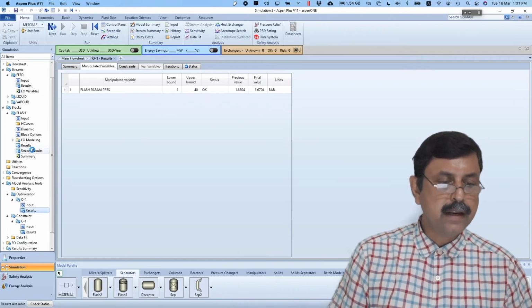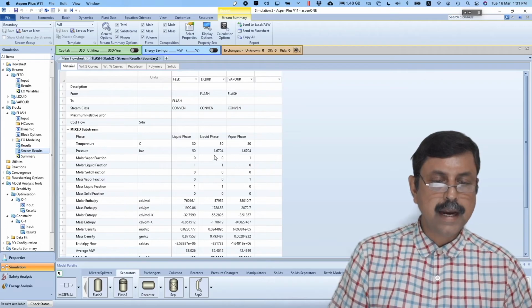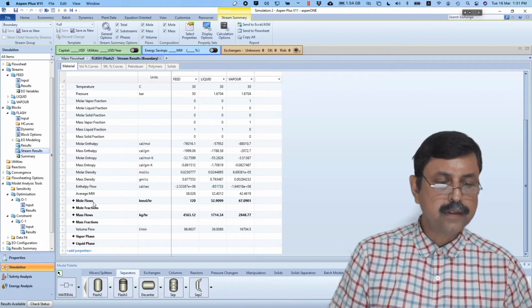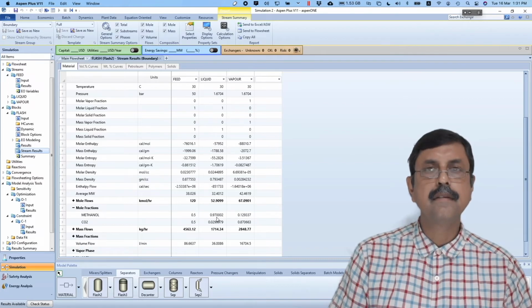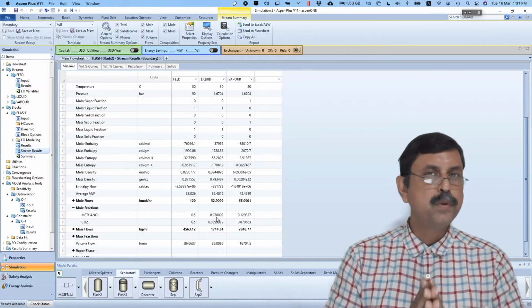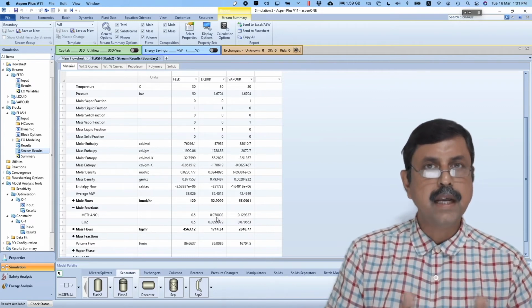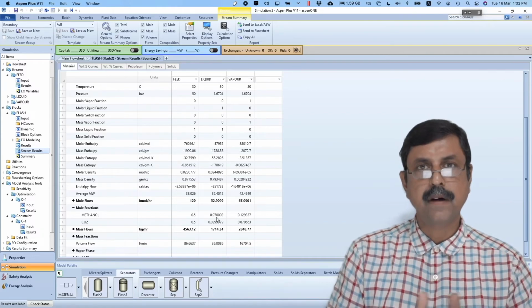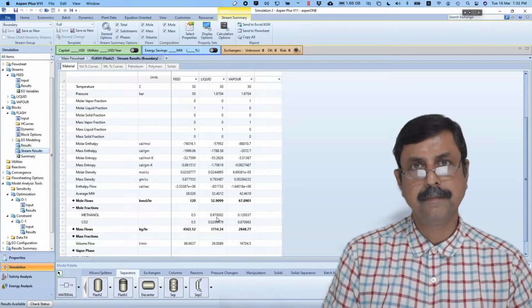And at that value, you see at this pressure, what is the mole fraction of methanol? It is 0.97. Okay, so you have put a constraint in the methanol recovery. Accordingly, you have redone the optimization and found a renewed result, which is constraint optimization.